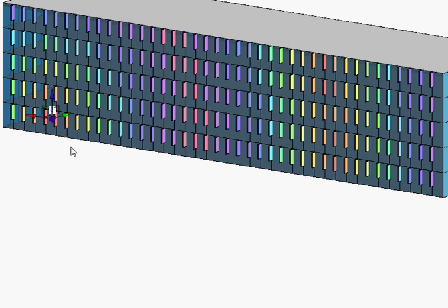Okay, we can see a facade here, which I demonstrated previously. It's made up of a matrix of nested adaptable components. Each one of those components has a couple of adaptive points, one to locate the fin on the surface, and the second one is linked to this control point. So they all share the same control point.